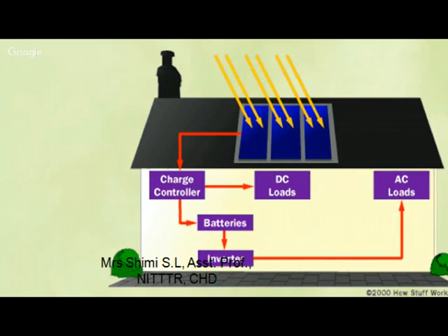So say for example you have a 12 volts battery, so you have to charge the battery. So this PV panel, say for example you have taken a 37 watts PV panel, and your output voltage is around 17 volts. So this 17 volts, you cannot give it to your battery. Battery may get damaged, is it? So what do you require there in between? You require a regulator, or you can say a charge controller.